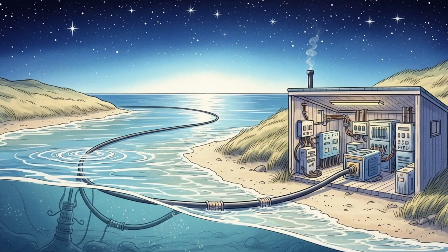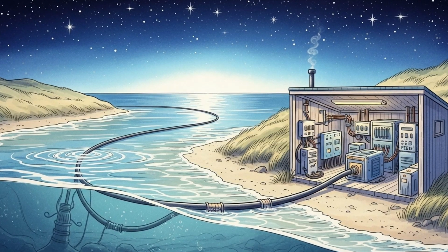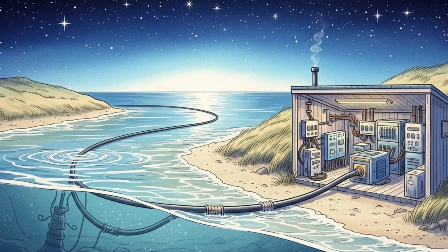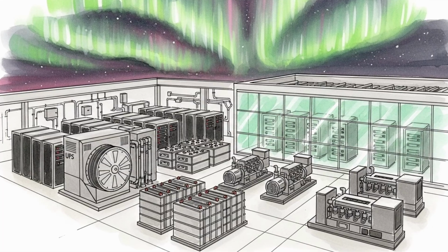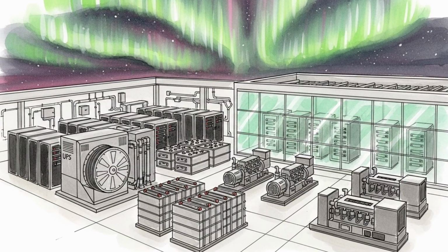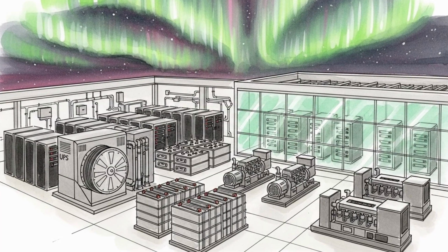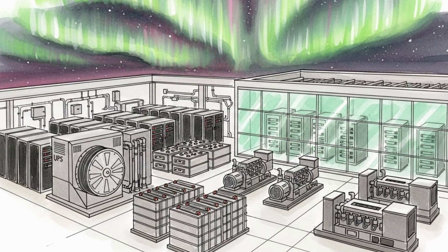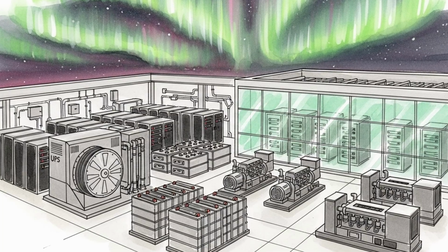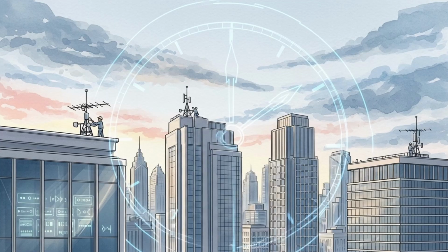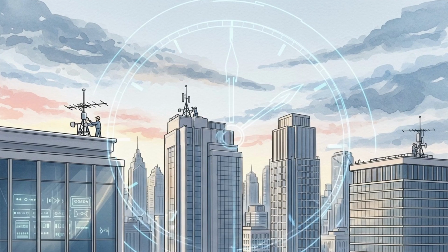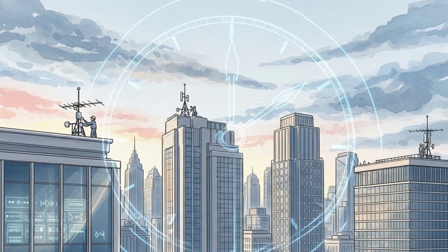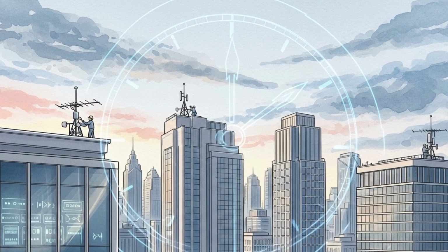In practice, monitoring and forecasting work as a layered filter. Days ahead, images of the corona and heliosphere frame the risk. Hours ahead, propagation models provide an arrival window. Tens of minutes ahead, L1 measurements confirm pressure and magnetic orientation and set the final expectation. On the ground, regional models turn dB by dt into electric field estimates and into actionable numbers for specific assets. This chain does not remove the hazard, but it narrows uncertainty and supports timely, proportionate responses.